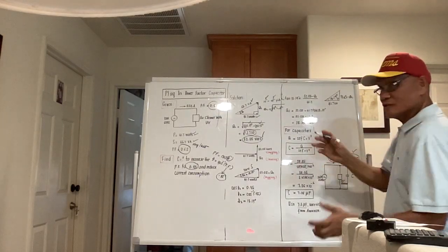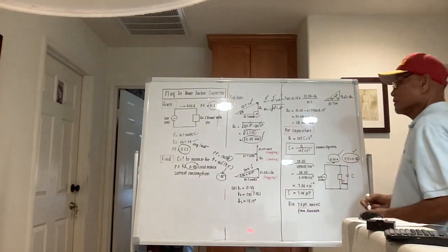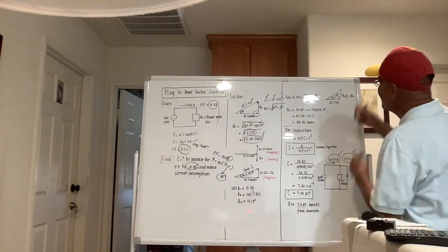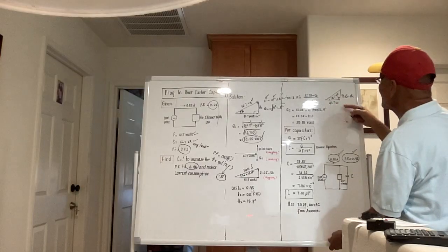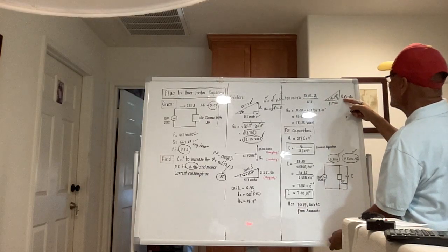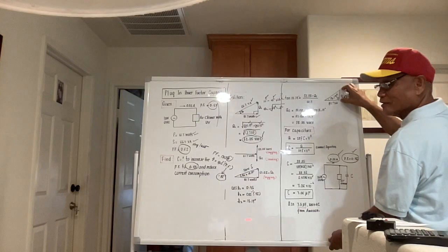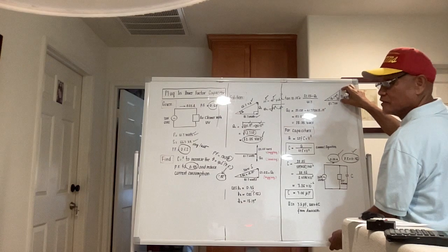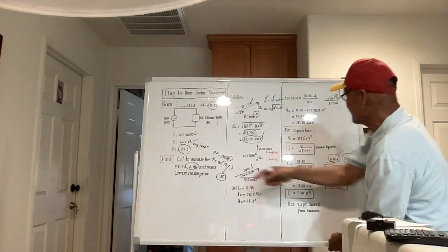So this is now the study of trigonometry for those who are not electrical engineers. This angle here is given, 18.19. This is 41.7 watts. This is 52.05 minus Q sub C, the overall reactive power. There is still a reactive power which remains, but it is not so much, because the desired power factor is just 0.95.